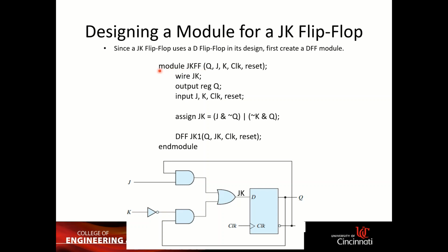You start everything similarly, module and endmodule. You define all of the necessary inputs and outputs. So you have inputs J and K, you have the clock, and also, different from this picture, you also have reset.